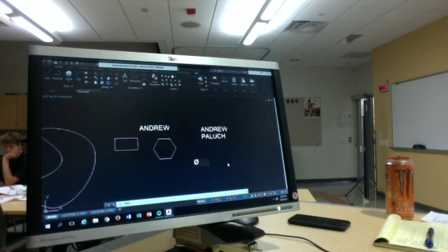You can also do, let's say it's 125 degrees out. You can't find the degree symbol. You type in %%D. Degree symbol. Or let's say you have a tolerance. It's 25 long, but it's plus or minus 0.25. So you can do %%P, and you type in 0.25.